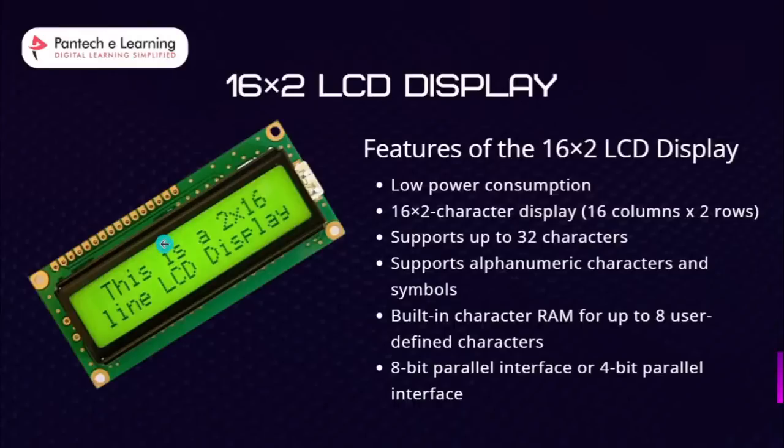It supports up to 32 characters, 16 columns and 2 rows, and it offers various features such as character generation, display data RAM and display on/off control. This LCD controller communicates with the microcontroller through an 8-bit parallel interface or a 4-bit parallel interface, depending on the mode selected. It is widely used in applications such as industrial control systems, consumer electronics and automotive displays.